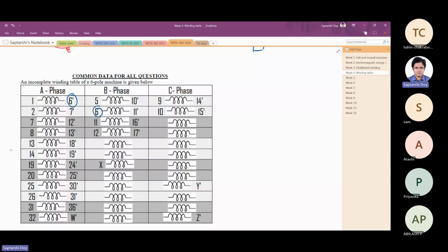we are not going to see more than double layer in this level. So definitely this is a double layer winding, because number 6 slot is definitely having two coil sides. The return side of coil 1, let us call this coil 1, and the going side of coil 6.